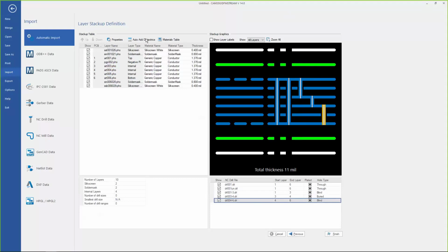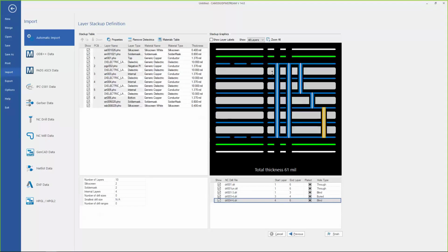More about the layer Stackup, I can take Gerbers and actually add dielectrics to them. And if I wanted to change any of these, and this is important, if I'm either a designer or a fabricator and I'm just trying to create a stack up, let's say an impedance stack up, and I do get some suggestions on different layer thicknesses and so forth from my fabricator, I can come out here and make those changes, and then they're reflected in the stack up.